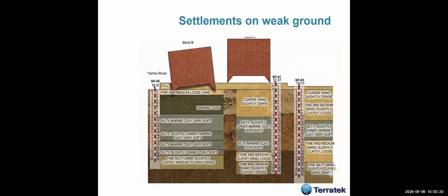As you see, this one was built over coarse sand, and of course with soil with reasonable bearing capacity. And this one was built on organic clay. So this is the reason. Probably there was not a good site investigation beforehand, and they just copied the design.